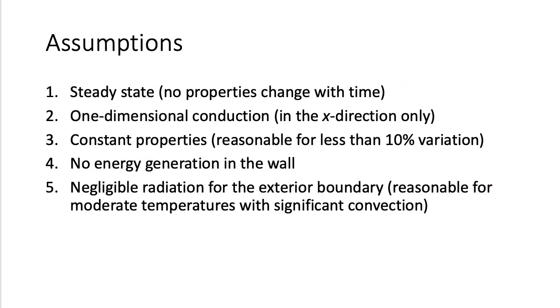Our first assumption for this problem is steady state, which means that none of the properties are changing with time. Our second assumption is one-dimensional conduction in the x direction only, which is based on the information provided in the problem statement. Our third assumption is constant properties, which is reasonable as long as the properties have less than a 10% variation over the range of conditions.